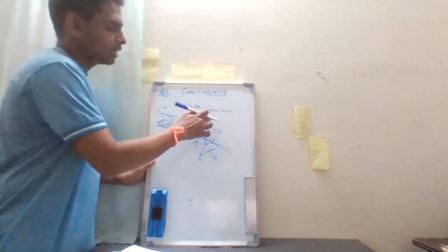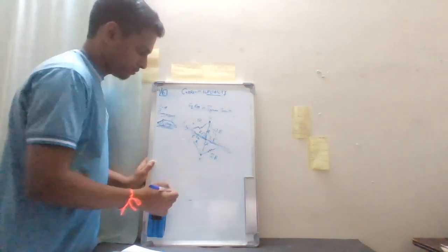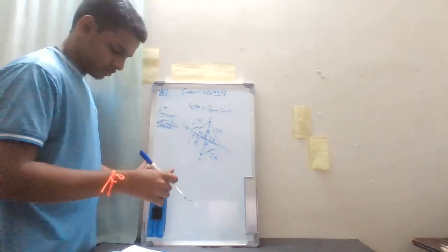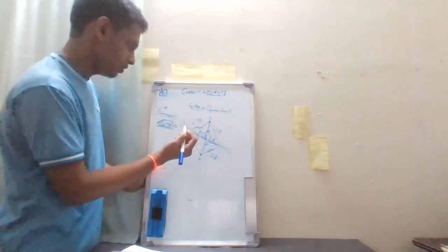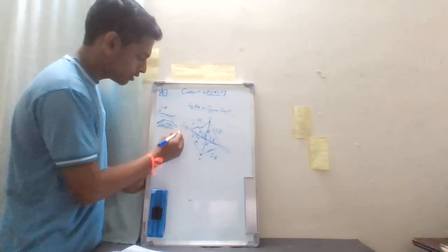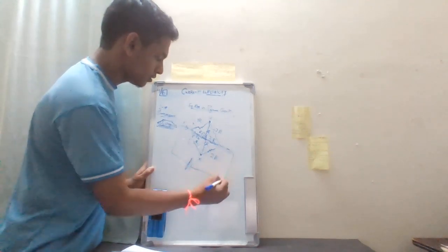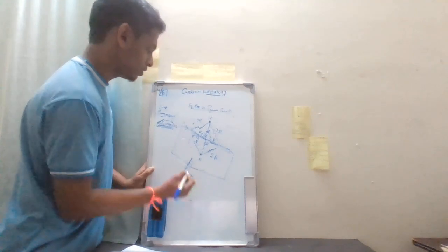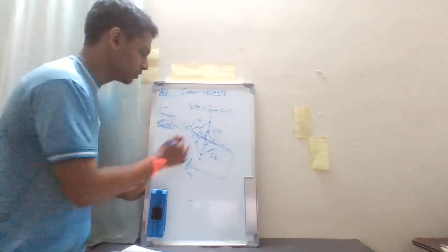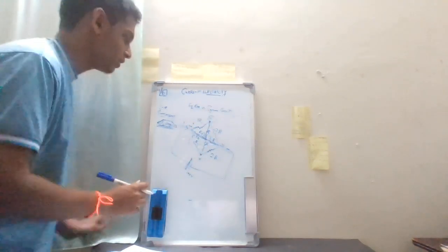Now, if we apply, yeah, we can apply KCL here, can't we? Yes, we can. That would be, here, it is given to be V volt, 100 volts. So this would be 100 here, 0 here. Now it would be much easier. So now we can apply KCL here.